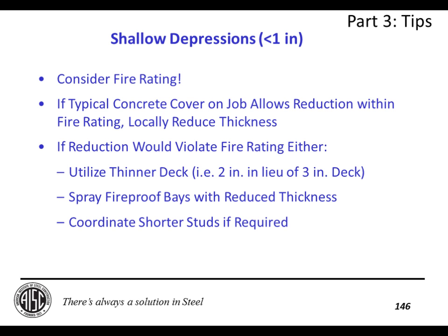But if that reduction would violate the fire rating, I would either use a thinner deck. So if you have a 3-inch deck on your job, you can locally switch to a 2-inch deck and buy yourself an extra inch for your slab depression. You can also go the route of spray fireproofing the bays that you need to with this shallow depression in order to get around your fire rating. And don't forget to coordinate locations where you might need to use shorter shear studs in order to not protrude from the slab.